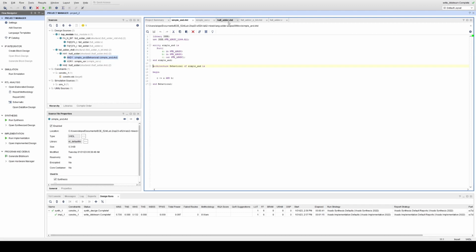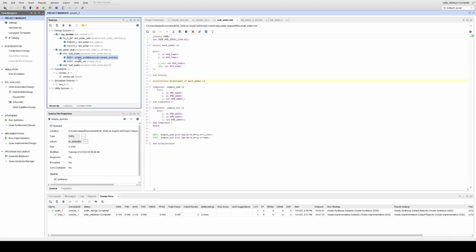And here is my half adder, which is used in VHDL. And now to actually use the AND and exclusive OR gates in this module, we declare these gates using the keyword component. A component is a reusable module that can be declared inside another module. Instead of designing a complex system, we can use these components to separate the design into smaller pieces, creating a hierarchy of components. And if we actually set this as top, we can see the schematic on how this actually works.